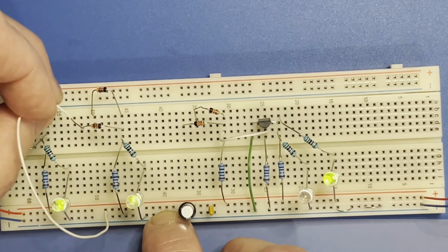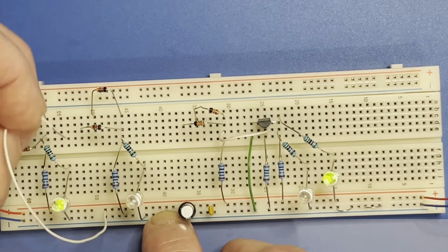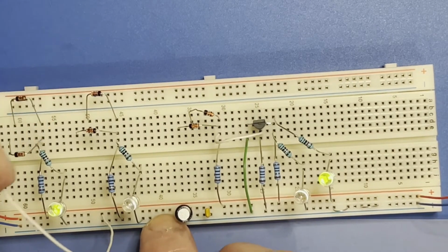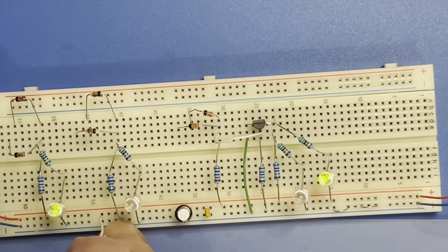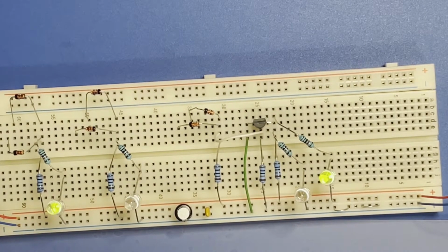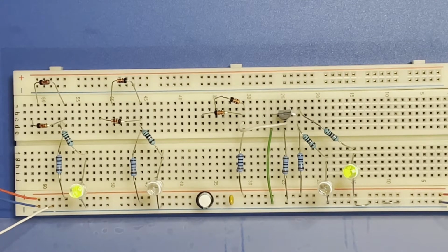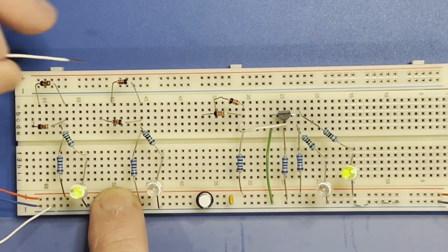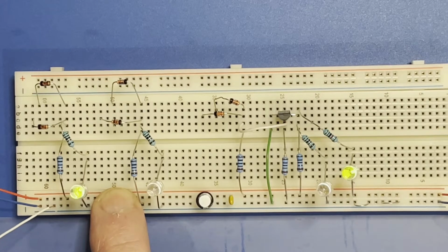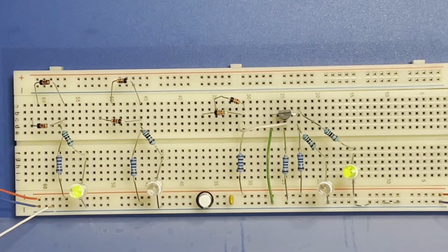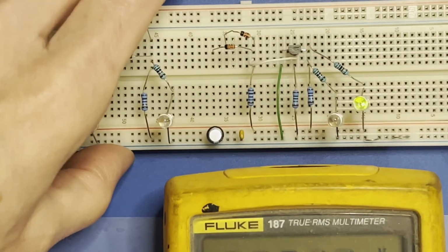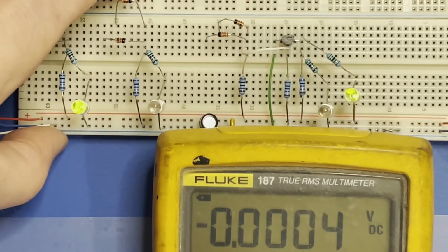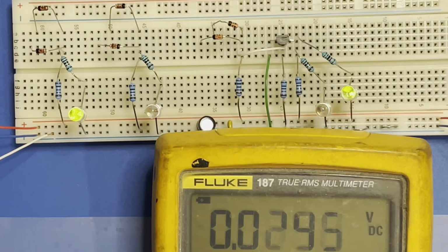Now the problem with that, as it is, it will switch fairly cleanly because it's not doing anything. Connect it to something else and you get problems. As they are standalone like that, they're okay to demonstrate the logic functions. However, you cannot cascade them, or mixed types should I say, because the output level of one is only held by a resistor, and the next one is also a resistor, and if the resistors are to opposite power levels, voltages, they fight each other and you don't get a sensible level.